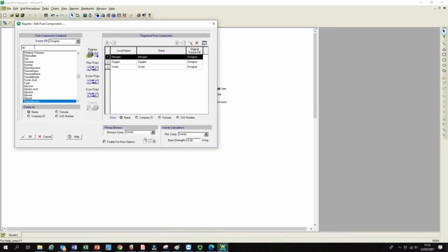First let's load heptane. Heptane is our solvent. If you type in this window, you will see heptane. Just double click it, and it will come to the right hand side. And then we have 2 hypothetical materials. One is compound A and one is compound C. Obviously we cannot find them here, so we have to create them.